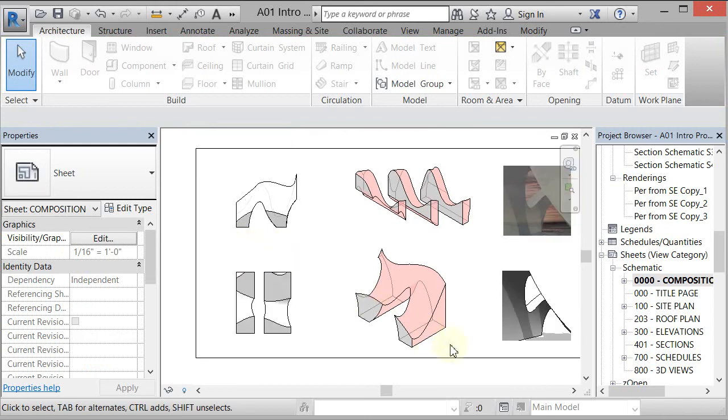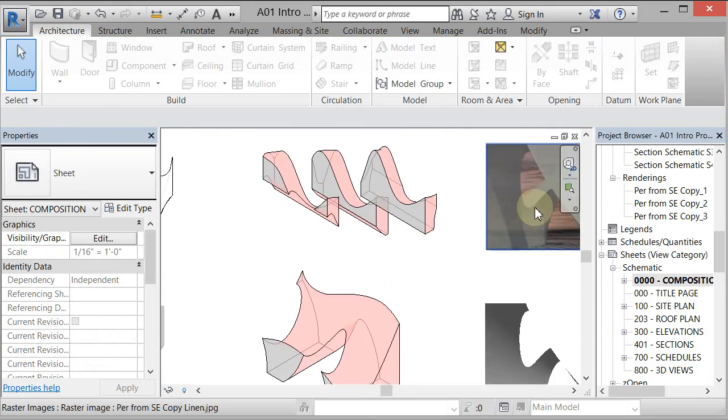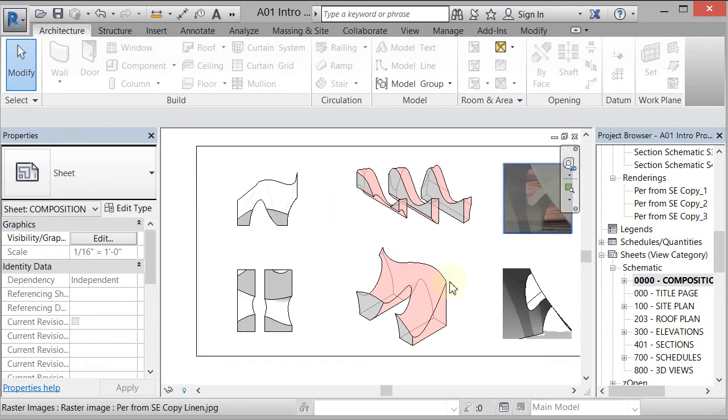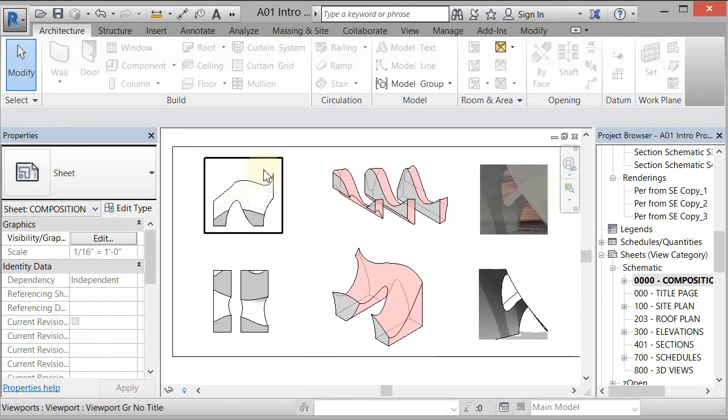And so I have some 3D views, a plan, that section, and then I have done a quick rendering up here and set them on a sheet, and now I can print them. Now the nice thing is that if I update anything, like if I had updated that section, it would automatically update here and here for the plan and section. The other thing that you can do, which is pretty interesting, is I can replace that model that I just put in here, and it will section the new model up and just automatically update it to the sheets and all the views. So let's do that, and then we'll be done.